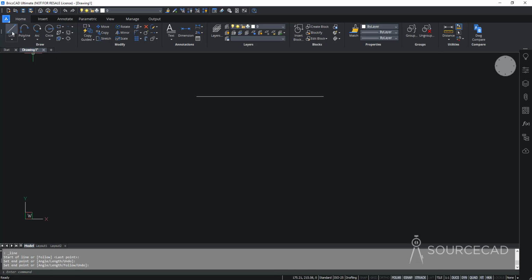So once again, I'll go to line, this point, and this tiny length is 4, enter. Now this angle here is 45 degrees along this clockwise direction from horizontal. So I'll first add the angle, and for that I'll press my tab key so that the highlighted option switches to angle. Then I'll type 45, tab key again, and this length is 3. So 3 and enter. There we are.